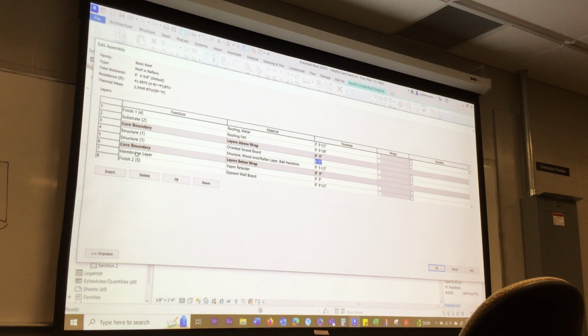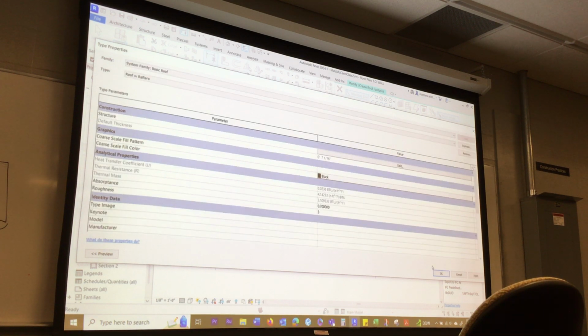Yes, sir? You need to change your strength or OSB. Oh, yeah, we need some, and roofs are 7/16, not 3/8. But framers like to do that, like put 3/8 on the roof, 7/16 on the wall, and the house is the wrong size, and the roof isn't strong enough, because the 3/8 is lighter. Now they have zoom booms, they don't do it as much, but back in the old days when they lifted it up by hand. Okay, so I think we're looking good there, yeah? Any other complaints? Thank you. Cool.